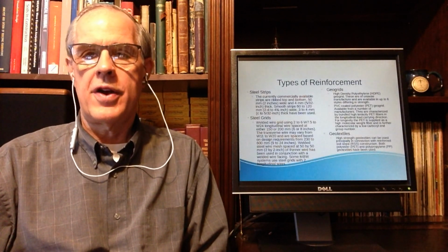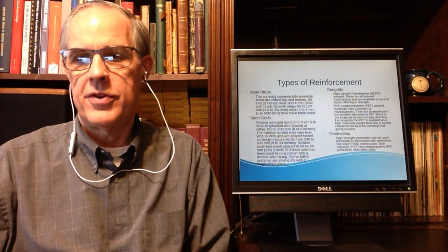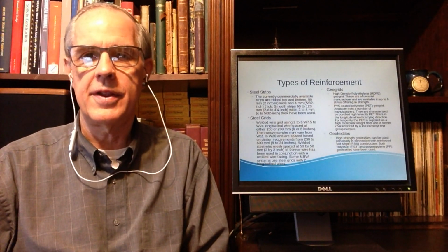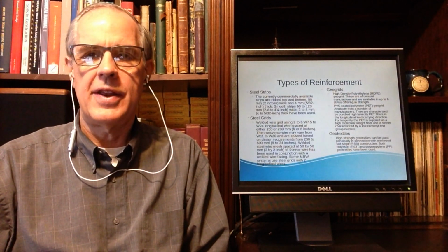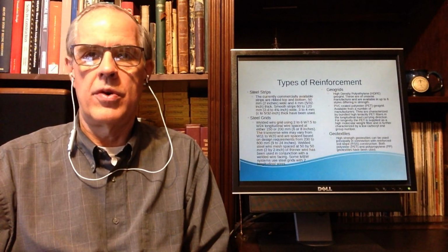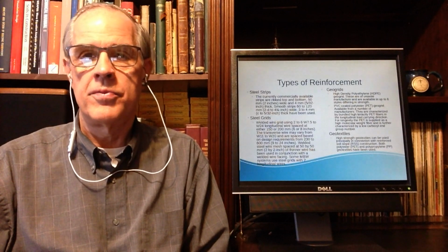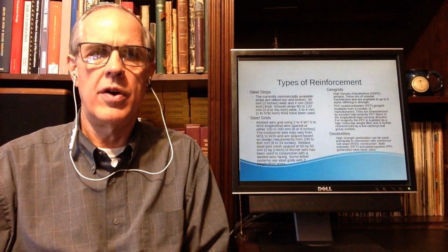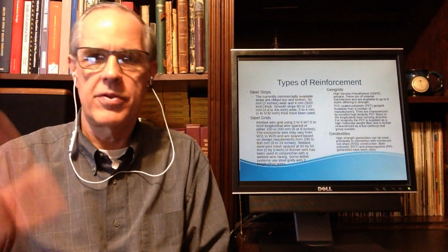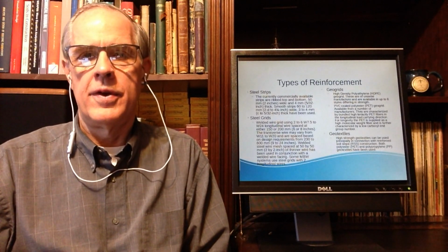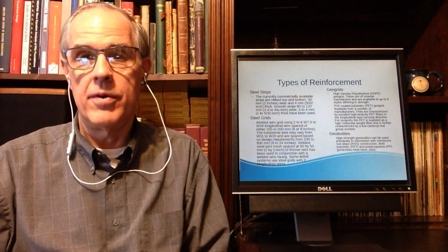There are two things I talked about earlier: the steel strips and steel grids that were used. Sometimes you still see these. The big disadvantage of steel strips and steel grids is their corrosion. They're more likely to corrode, and that's an issue, especially if you have water running through the backfill, or you have corrosive types of liquids flowing through, which hopefully you don't.